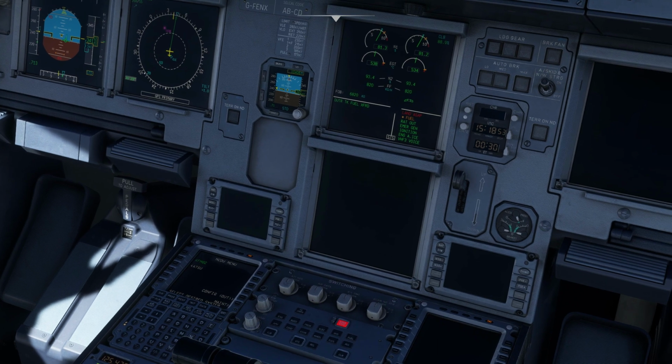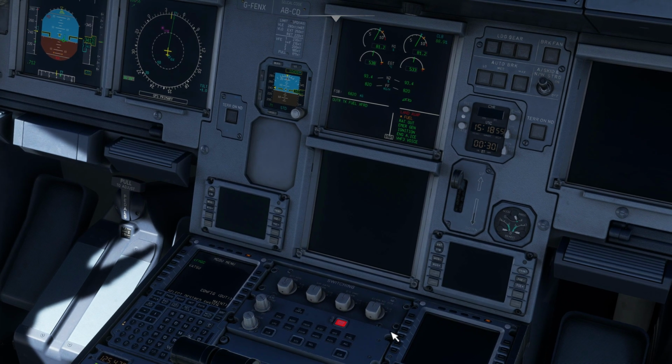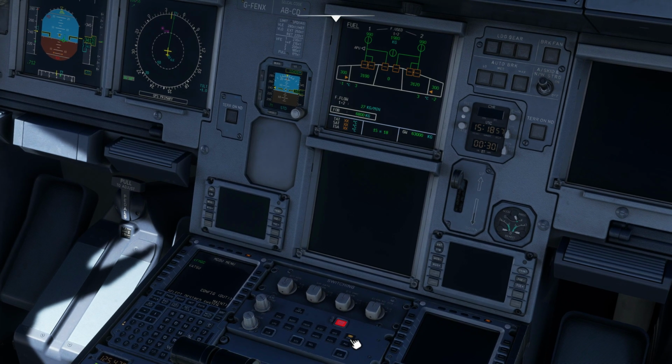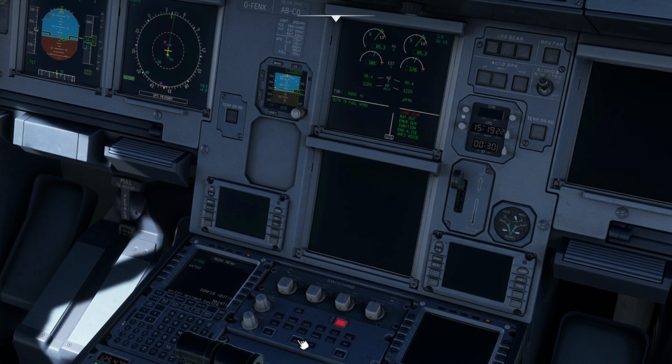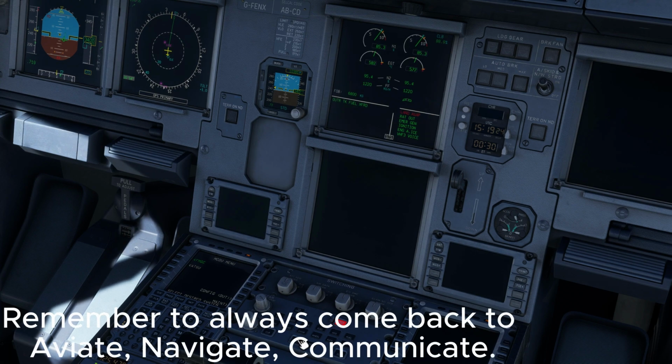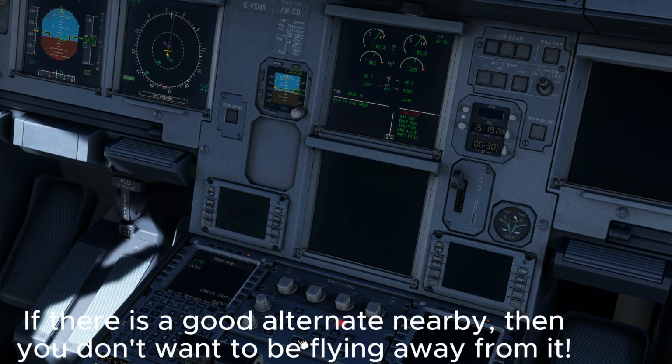Secondary failures show the fuel pumps, which have all failed. Fuel is gravity fuel feeding. Clear fuel. Clear. Okay, let's pause the ECAM. We have land ASAP in red, so we need to divert.